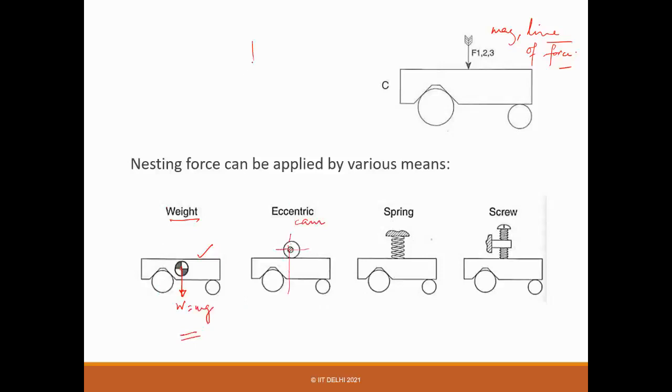An eccentric cam is like you have a point of rotation, so you have a pin, but one side is bigger than the other. So here the radius and here the radius are different. The moment you turn it, you will start squeezing it. This design is many times used in bicycles to quickly remove your tires or wheels, or even your seat. If you have any bicycle, you can look at it. There are many designs doing that.